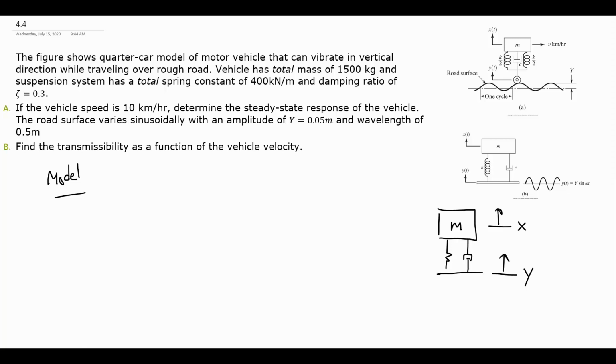So the platform can move, or the base, that's really the ground, is able to move up and down from some baseline, and that's going to transfer through the spring and the damper into our mass. So in reality, there is going to be a force acting on the mass, but the force is coming from the difference in displacement and the difference in velocities between the ground and the cabin of the car.